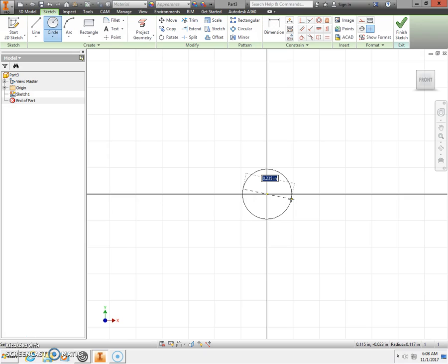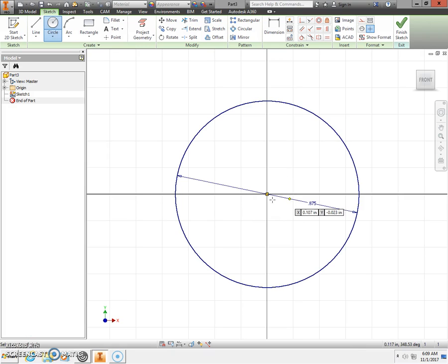to size your finger. When I used the circle template to size my finger, I ended up with 0.875. I could also, since it says in fractions on the circle template, type in a fraction, 7/8, and then press return or enter on the keyboard. Press the escape key. Now we're going to take an offset to give our ring our distance.